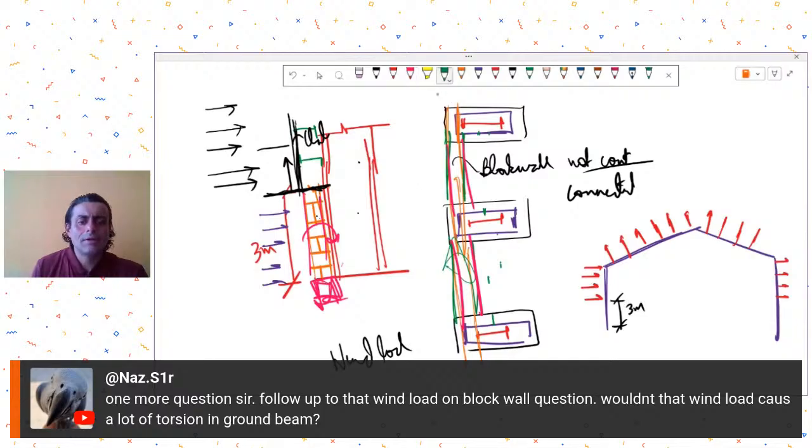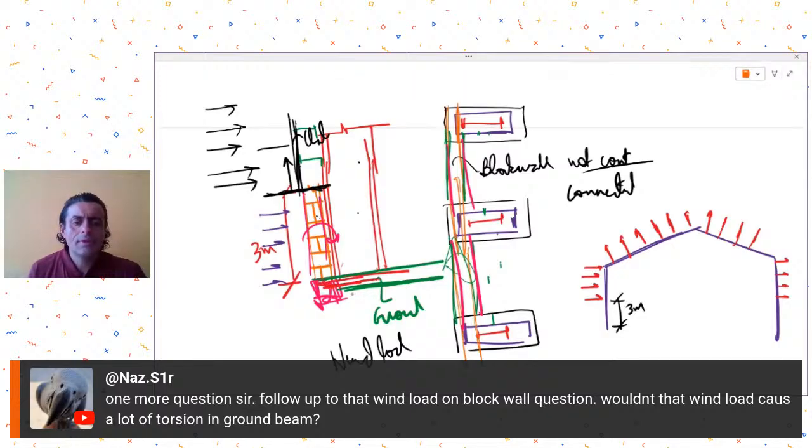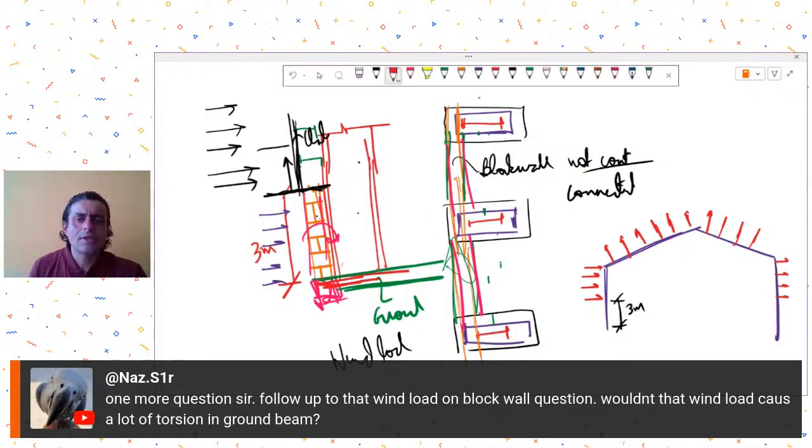Generally, many design engineers also consider that you are going to have a ground slab connected, and you can integrate it with the beams. When you do that, the effect of torsion will be reduced, isn't it? These ground slabs are also considered effective in providing lateral restraint to your pedestals.